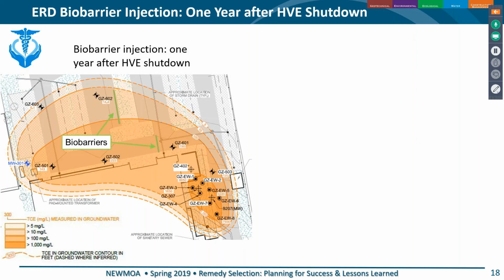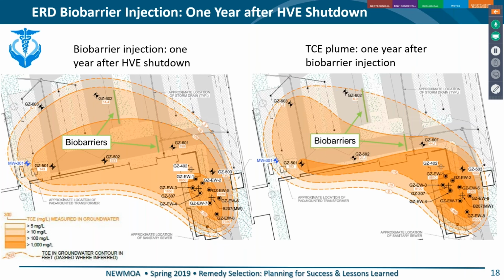So this works. And the reason there's 2 of those instead of just one nice one is that all of that lighter colored pavement that you're looking at, the parking area to the north, is pervious pavement. So we didn't want to disturb that at all. So we put these 2 barriers in. You can see 1 year after the injection that it's definitely working nicely. The northern one is working a little bit better. We still have that rebound in the source area.